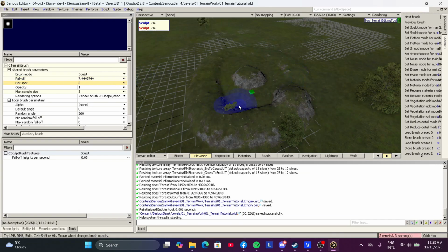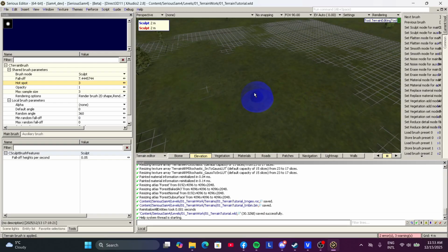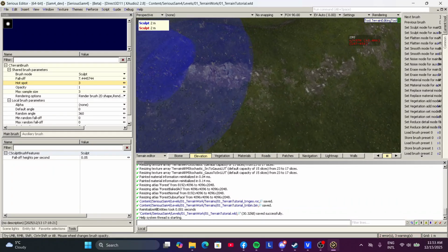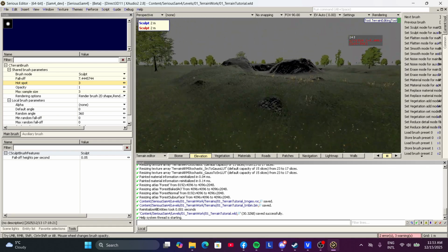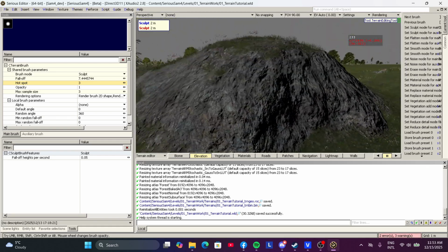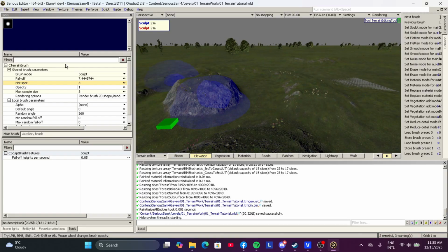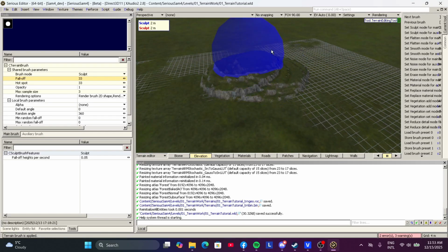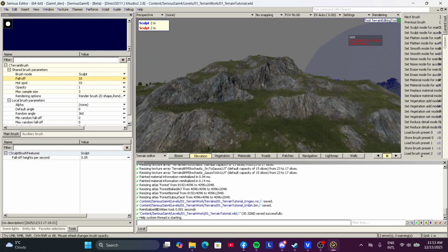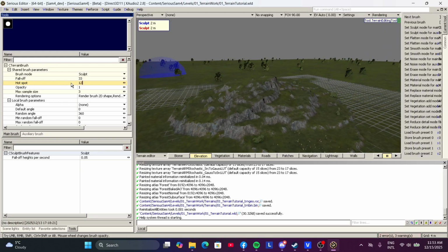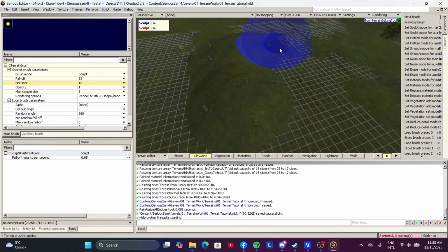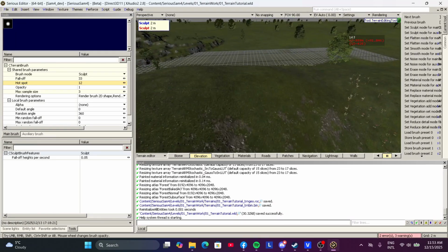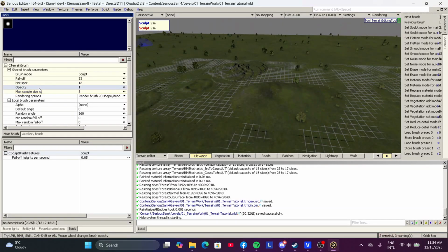But if you put it to 3, this makes it smoother. So it has like these bumps. This one has intense bumps because we use the hotspot of the same value as the falloff. So you can go crazy, like put 33 from 33 for instance, and you have it like this. And if you want it to be smoother, you can just put 12 at the hotspot, left click, and there you go. It's making it smoother with the opacity of 1.